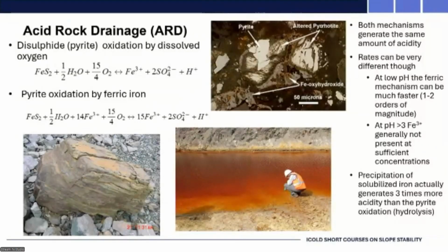Okay, so I'm touching very briefly on acid rock drainage, which everyone knows and everyone is familiar with. But what I did want to point out here is that it's mainly to do with pyrite oxidation, but you get pyrite oxidation not only being exposed to oxygen, but you also get pyrite oxidation when it's submerged. If you've got a lot of dissolved iron in there, you're actually going to produce more acidity than just from your tailings exposed on surface.